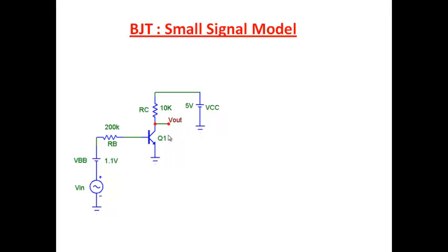And then on top of that, if you apply a signal voltage here, that signal travels to the base, modifies the base current, modifies the base emitter voltage, which causes changes in the collector current, and that results in a voltage which is proportional to the signal here. And if you bias it properly, if you choose all the resistors properly, you get amplification here.